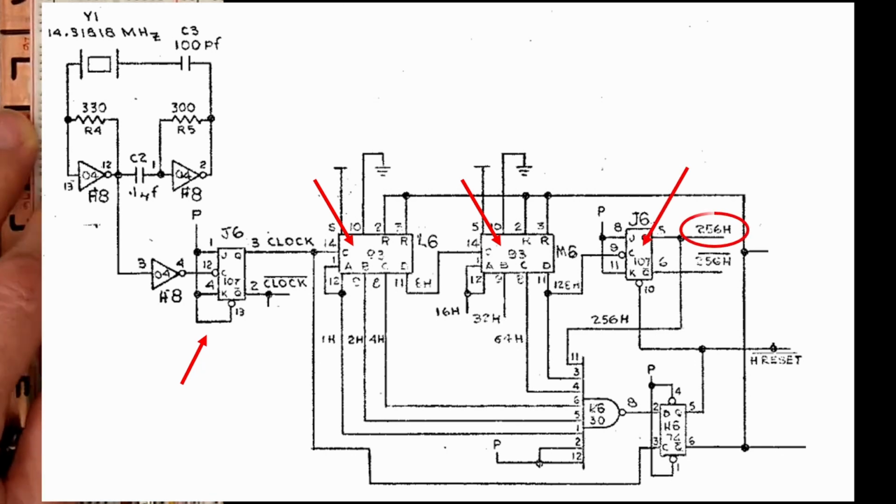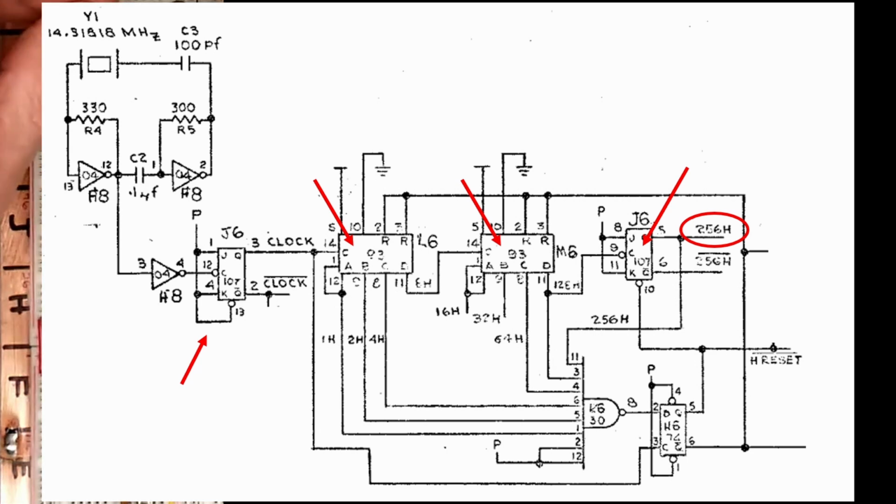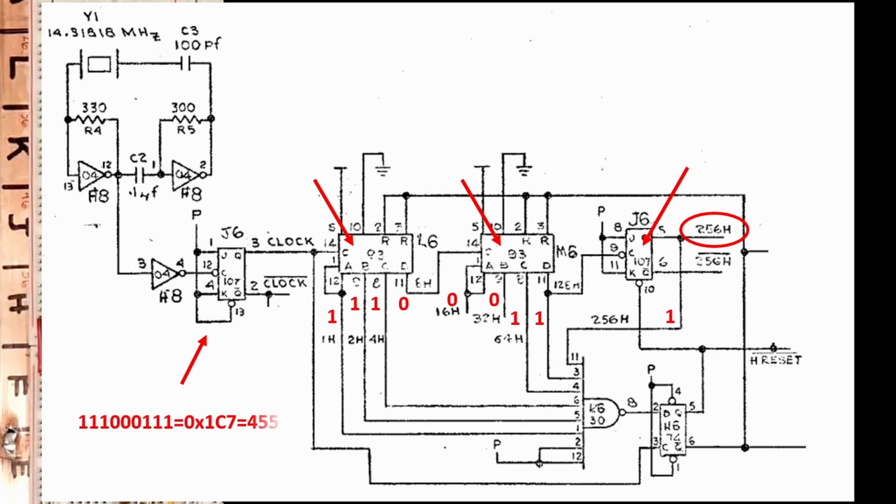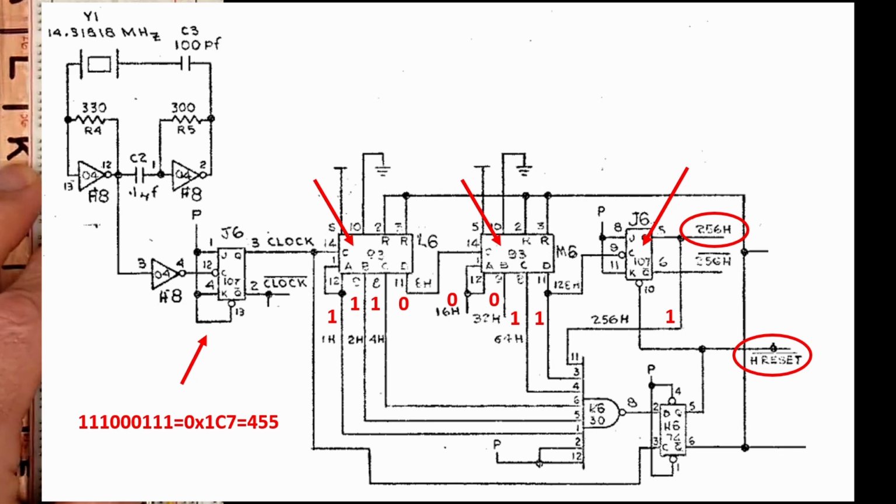get the 9th bit. Remember that if we divide the oscillator by 2, we'll need 455 ticks for a single horizontal line. You can't get that with 8 bits, hence the 9th. Most designs then check for the counter to hit around 455 and reset to 0.